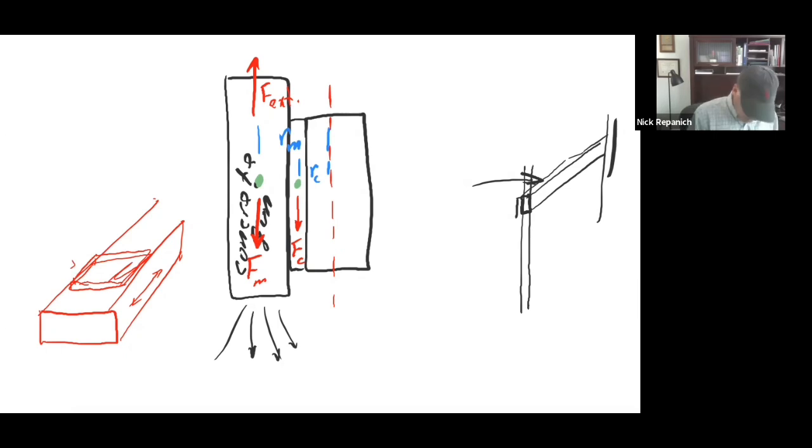You have a carriage. As we look at the different kinds of load on this and look at moment loading, there's going to be a moment load this way. You guys have had moment loading, right? This would be called the pitch moment, and that would be the moment this way on this bearing. So it'd be like the bearing doing a wheelie, back and forth. You would have a roll moment in this direction.